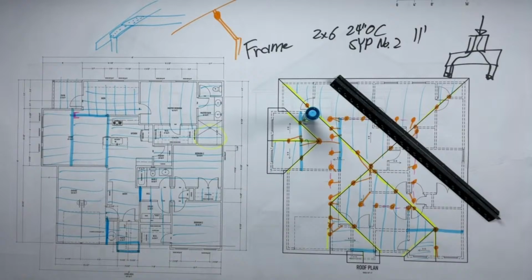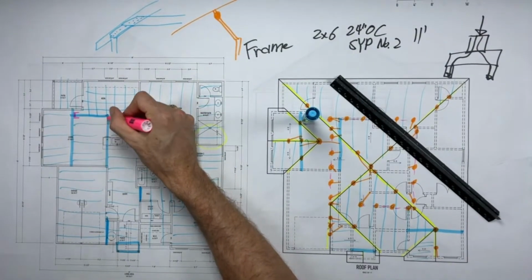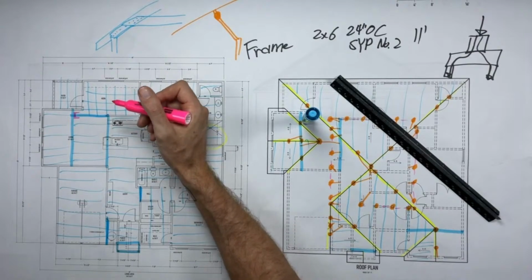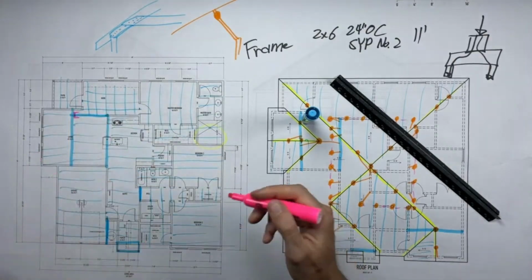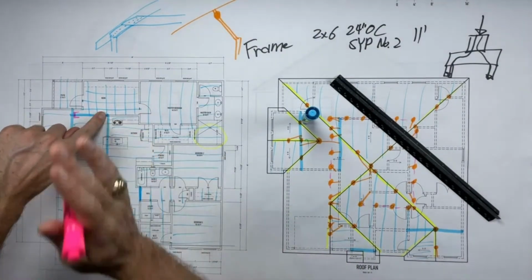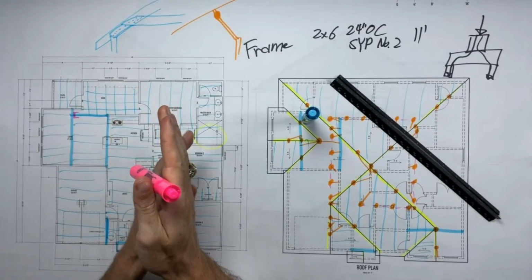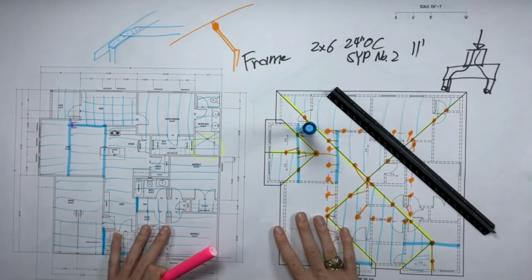And honestly, here's an interesting detail. Where this wall ended, if I was framing this, I would stretch the wall a little bit so I get enough bearing for this beam and this beam. But let's say in the situation where I only had the wall, and the wall ended and my beam was right on the end of the wall, and I also had to hang this beam. Well, what would I do? Here's what I'd probably do. There's multiple ways to do this.